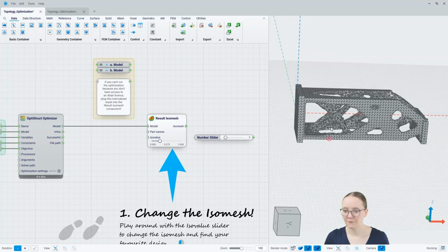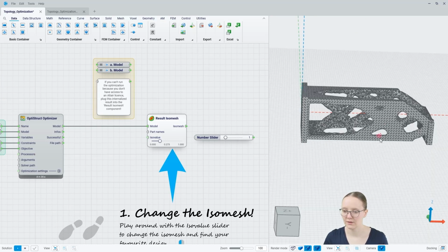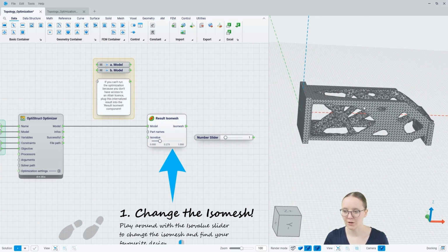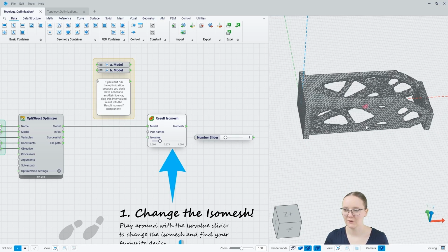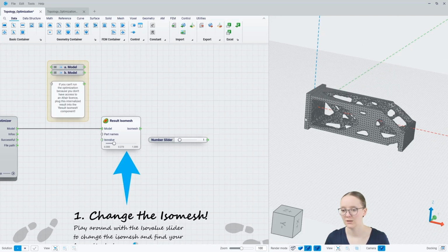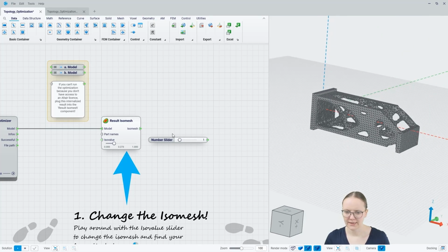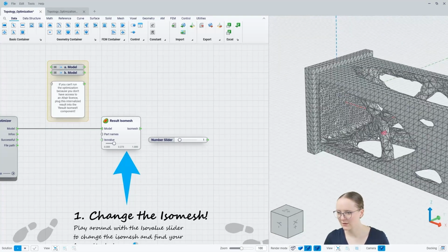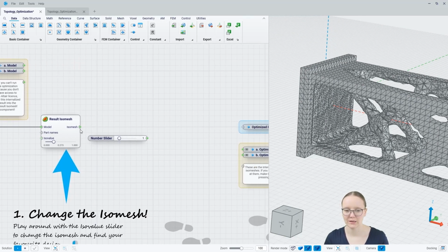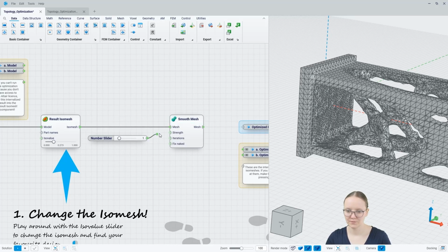As I mentioned before, this is the non-dimensioning topology optimization that I just ran. So we get a rod-shaped result, which is very discrete. All right, and the mesh doesn't look super nice, so I will just quickly smooth it to get a better looking mesh.